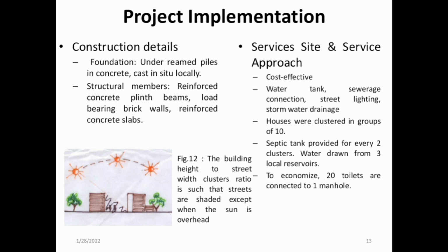Services site and service approach. Each family was provided with a plot having a water tank, sewerage connection, paved access with street lighting and storm water drainage. Houses were clustered in groups of 10. A septic tank was provided for every cluster. Water was drawn from 3 local reservoirs, and to economize, 20 toilets are connected to one manhole.